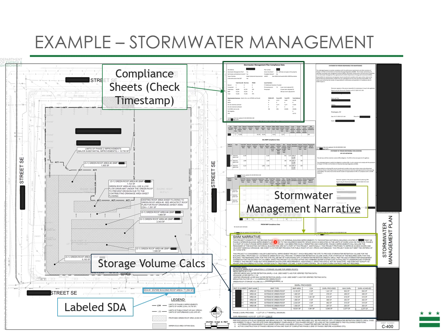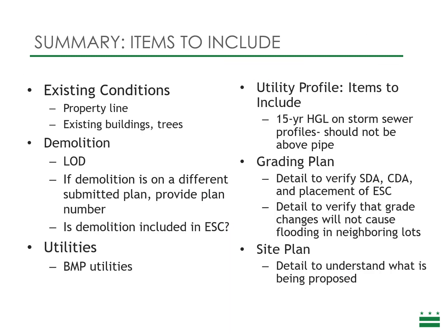Next, labeling the site drainage area and delineating it correctly is very helpful for a plan reviewer to check. Also, labeling the BMPs on your plans with the BMP ID that is given to that BMP in SGS is very helpful and useful for the plan reviewer to make sure that all of the BMP information is correctly entered.